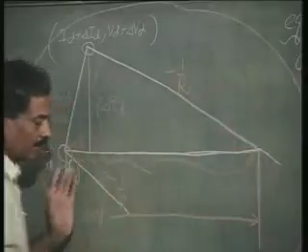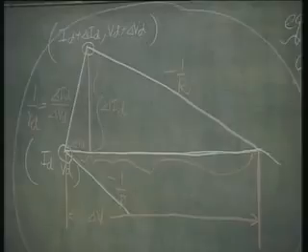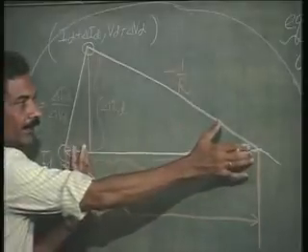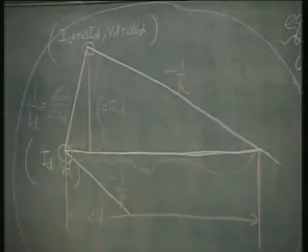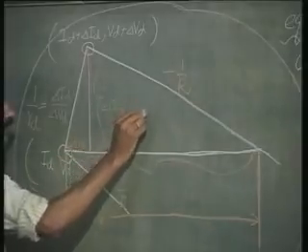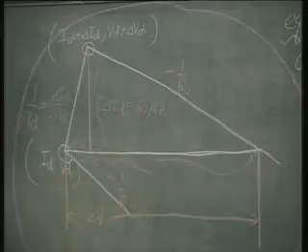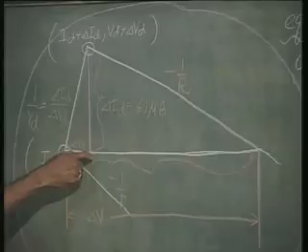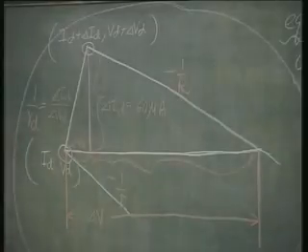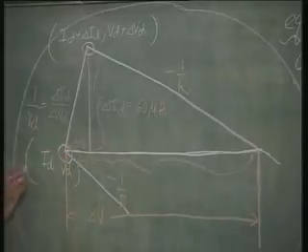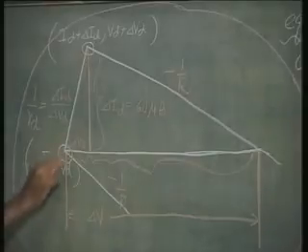That is the assumption. So, the change in current delta Id is nothing but delta V divided by R. So, that delta V was 60 millivolts, and this delta Id came out to be 60 microamperes. Once this is known as 60 microamperes and Rd is known as Vt divided by Id, which is 26 divided by 5.4 milliamperes, that is the slope around this point, delta V diode divided by delta I diode, which is the slope at this point.